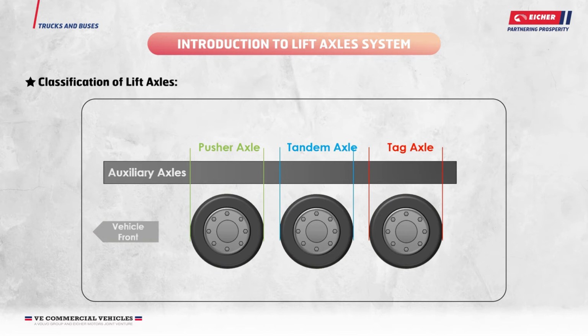It has 3 merits. Prevents unnatural tire wear due to carrying heavy loads. Prevents damage to roads and bridges by distributing the load over an extended area. Reduces wear and tear of the main axle by providing additional support.